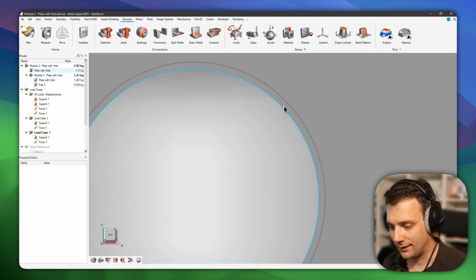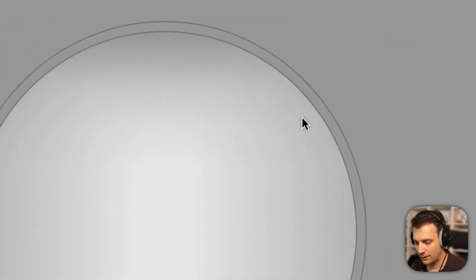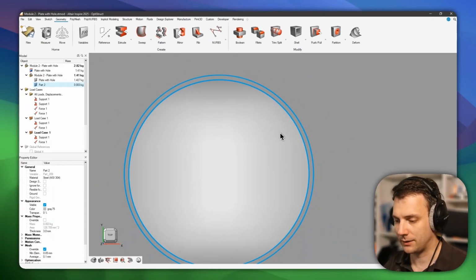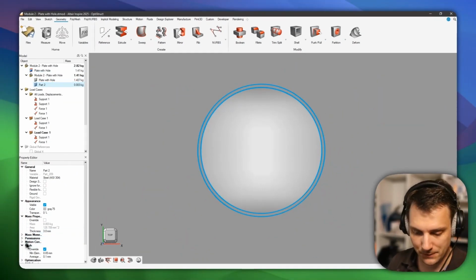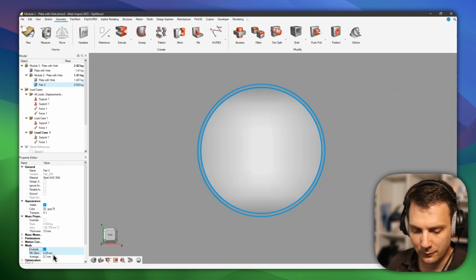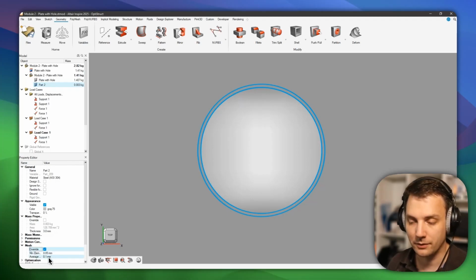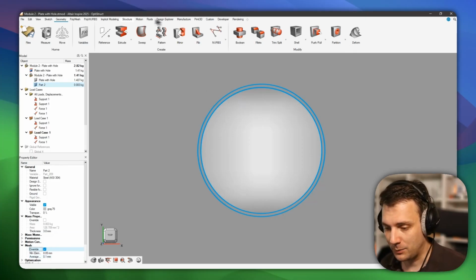And so what I did is I just created a partition with geometry partition. And then I just said, okay, I think my default mesh size stays at 1 millimeter, but I have said that this surface here, the partition, has a mesh override, and up here, you see that I defined a 0.05 millimeter minimum mesh size, and 0.1 being the average on that surface. And so what this gets me then is, let me see if I can get the results back here.